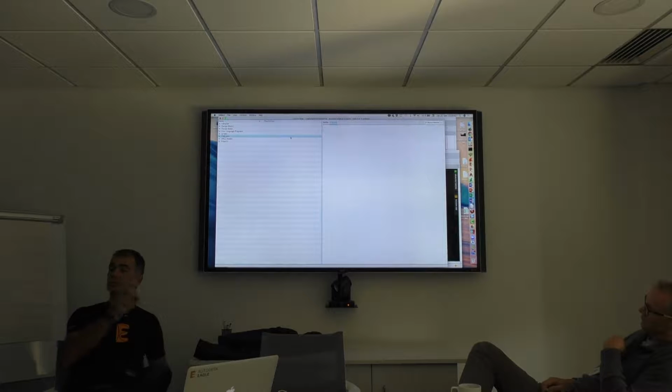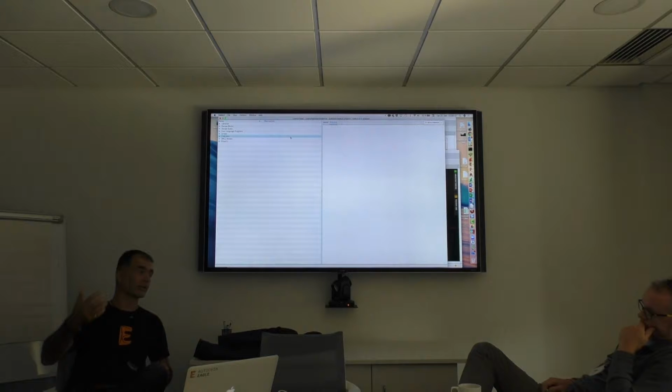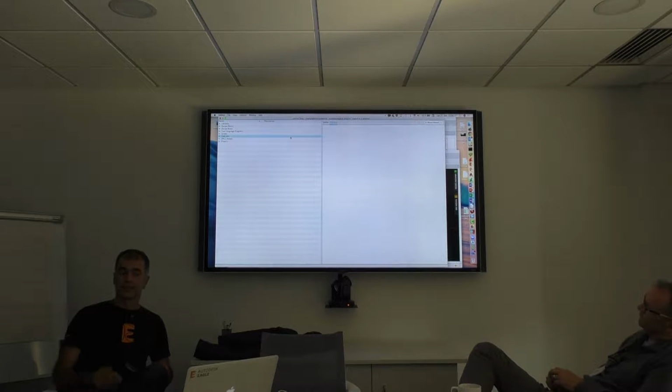So in the schematic, you draw signals between the components. You have a resistor that's connected to a capacitor. We call it a net. If I go into the board, I have to do a trace, a copper line on the board that connects this again. This is something you can do manually. You can use a kind of auto router. We have some functionality, we call it quick route and so on. So that's quite convenient.